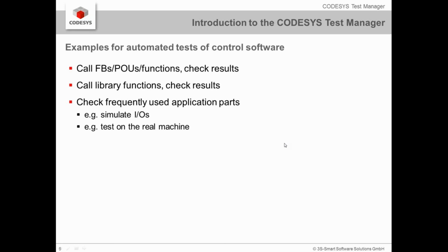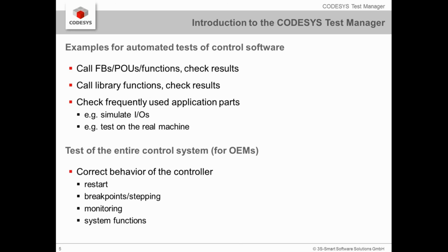Then we can use the Test Manager for frequently used application parts in order to simulate IOs or to test the real machine, to make a real regression test or a system test on the machine side. So this is the case for the application engineers, but even device manufacturers, original equipment manufacturers, can use the Test Manager in order to test their entire control system.